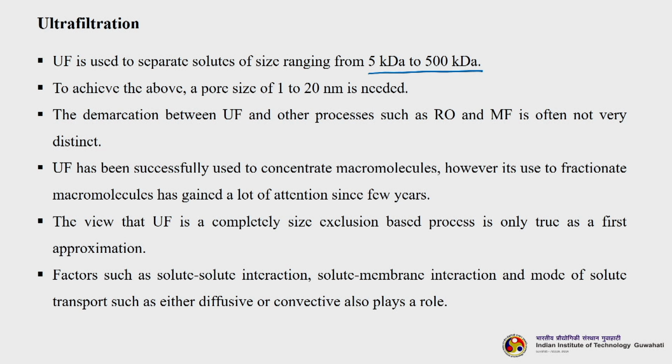So, to achieve this, what should be the pore diameter or pore size of the ultrafiltration membrane? It is almost 1 to 20 nanometer that is required to reject 5 kilodalton to 500 kilodalton solutes. Please note that the demarcation of ultrafiltration and other membrane processes such as reverse osmosis and microfiltration is often not very distinct, but it depends on the size of solutes that they are separating, and of course, the type of membrane as well as the pressure range that is required to do the separation.